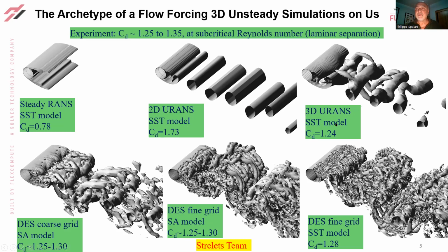And in this case, we were very lucky with the drag coefficient, but the simulations depend too much on which turbulence model you're using, how wide the period is in your simulation. So 3D URANS, I don't think has a future.